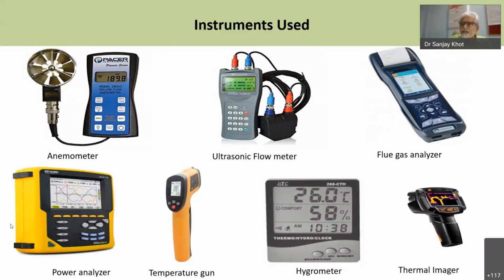Generally we install this power analyzer and connect it for 1 hour, 2 hours, or somewhere for the full day, at particular locations. Those locations are where we decide we want to monitor all these electrical parameters continuously for 24 hours. The novelty of this instrument is that you can log and record everything, and further it can be analyzed. On the basis of the analysis, some inferences are taken, and then some recommendations are given to the industry.